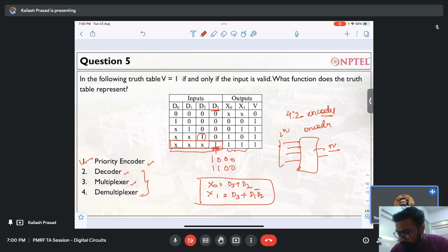Similarly, because I have taught you how to write the equation for multiplexer, and similarly how to write the equation for decoder, you have to write the equation for demultiplexer also, and for encoder also. So write demux and encoder. And you can take any of these circuits and think, if I want to design a half subtractor, or a 2-bit multiplier, how will I do it? If you are able to come up with the solution, then the goal of this tutorial is done. Okay, so that's all from my side.